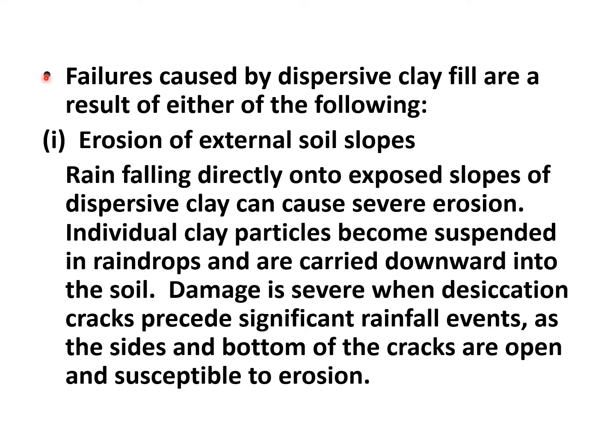Failures caused by dispersive clay fill are a result of either of the following. Number one, erosion of external soil slopes. Rain falling directly onto exposed slopes of dispersive clay can cause severe erosion. Individual clay particles become suspended in raindrops and are carried downward into the soil.